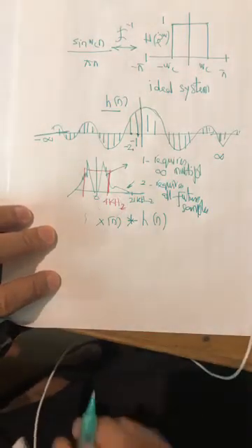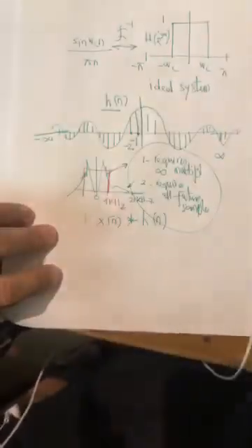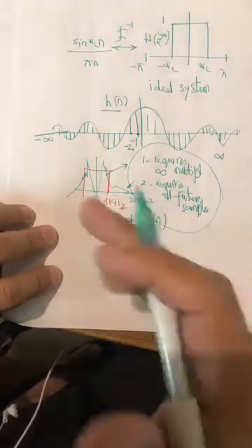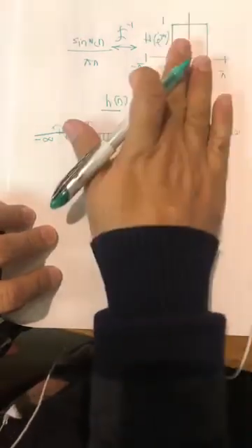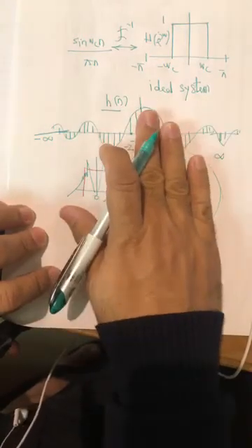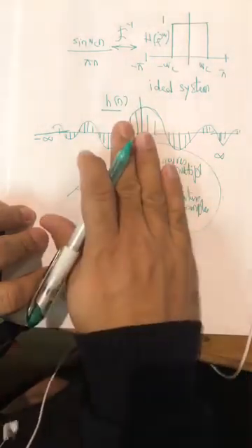Obviously, it's a live broadcast, or you are talking to somebody on the phone, and you cannot just collect all the samples till the end of your conversation and then pass them through a filter. It does not make any sense. So this is non-realizable. This is an ideal system. We want a system to be like this, but it is non-realizable. This is the main problem with an ideal system: you cannot realize it. It means you cannot write a computer program to implement this system.